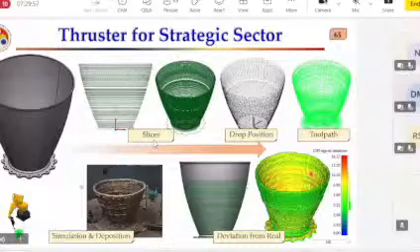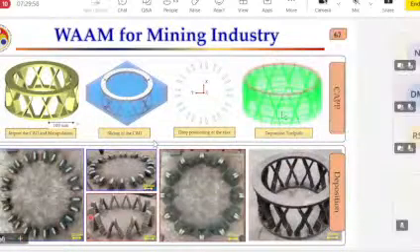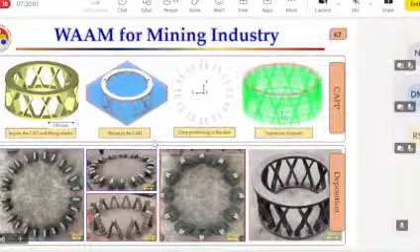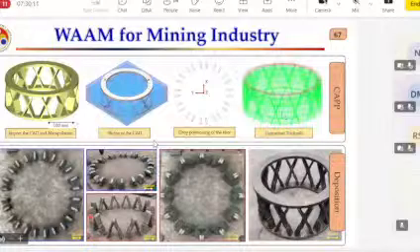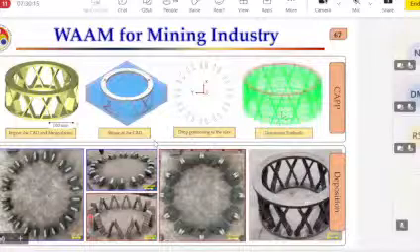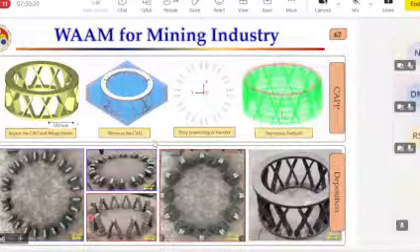We're able to handle the heat accumulation, because we're depositing one drop over here, then the next drop over here, next here, like this. This helps in cooling the region at a faster rate till it reaches back to over here. Hence, there is no issue of overheating and dripping of material at height as well.